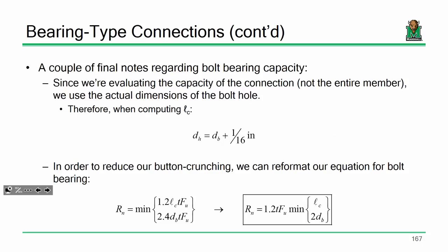Okay. All right. Now here's where you're not going to like me very much. You're not going to be happy with me on this one. So before we talk about bolt layout connections on Friday, I got one final parameter to run by you that you're not going to like. So when we calculated net area before, when we were looking at tension members, we said, all right, when we calculate a hole diameter, we take a bolt diameter and we add 1/8 of an inch, right?